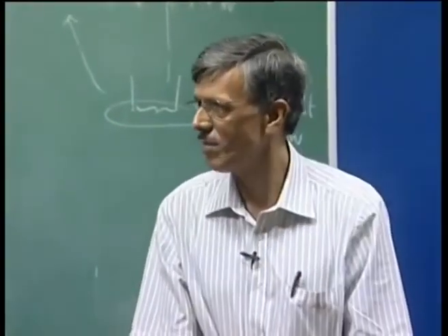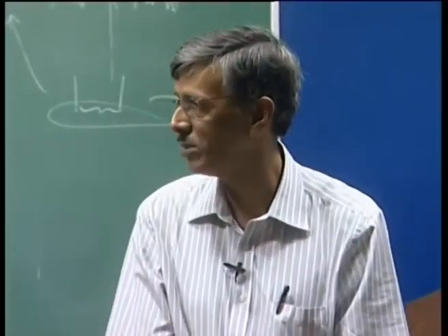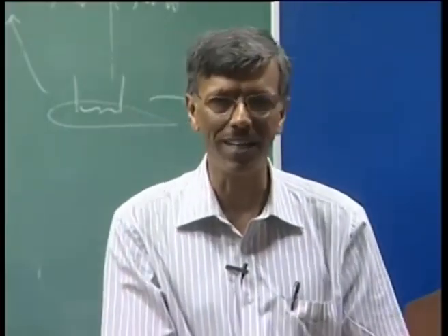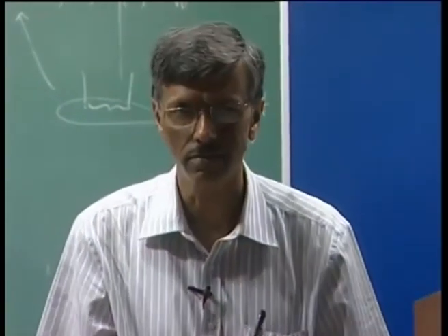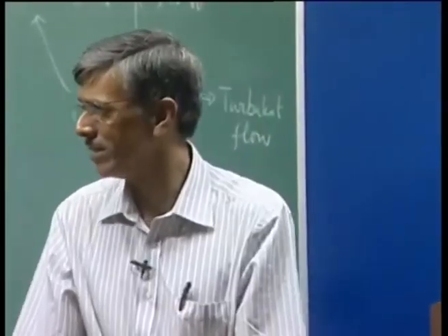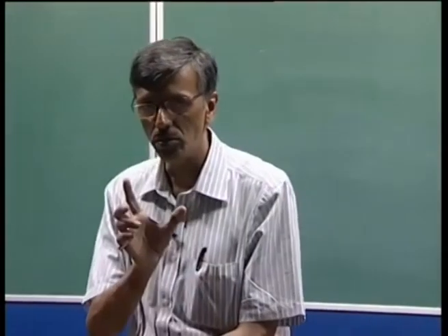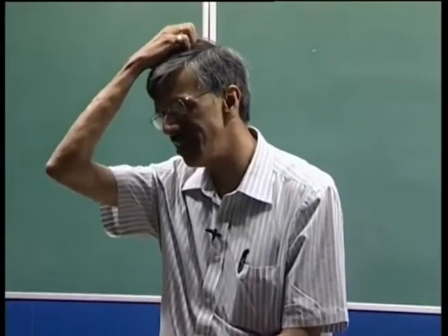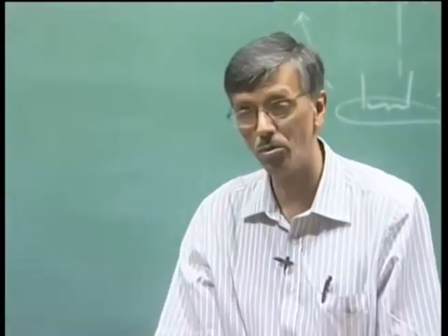So, we are going to use POD, proper orthogonal decomposition, as a tool in trying to understand turbulence. You see, turbulent flow may look chaotic, but still within that chaos you would see some pattern, right. Those patterns are what are called coherent structures. So, this was what was attempted. POD as a tool allows you to project that stochastic system into a deterministic basis and see whether you can pick up those coherent structures or not. That is what we are going to spend quite a bit of time on.